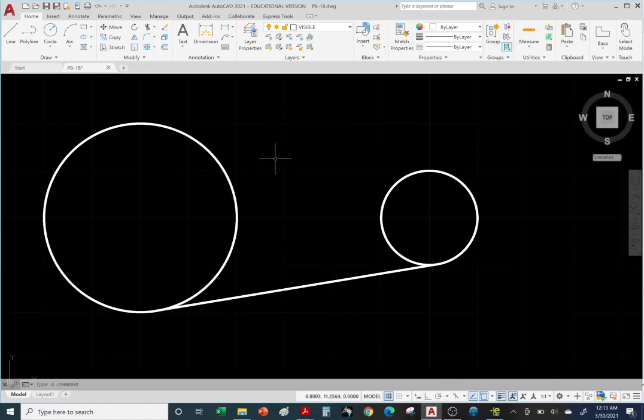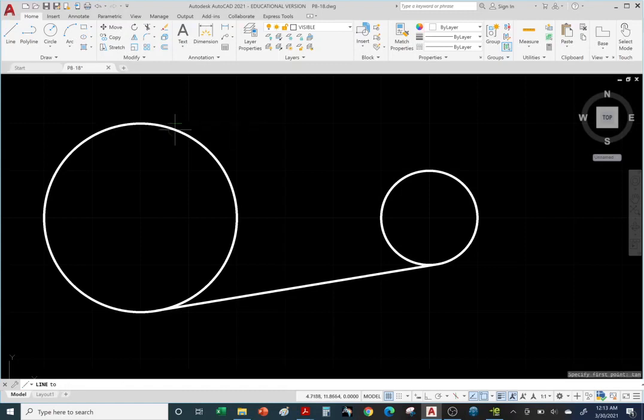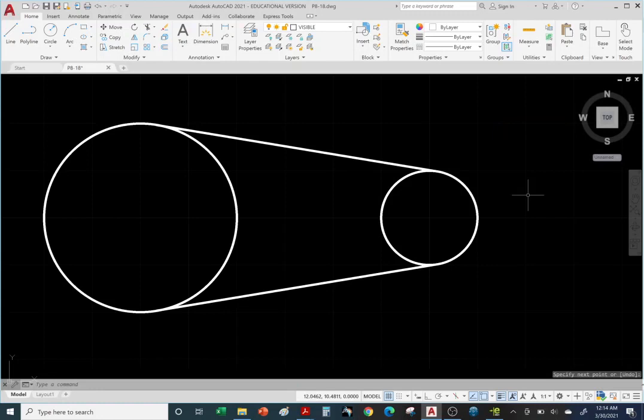So let's repeat the same thing at the top. Line command, then type in TAN, enter. And look for the green lantern ring, which guarantees tangency, click. So now it's tangent to the top. Now let's go over to this side, type in TAN again, enter. As long as you click anywhere on the top portion of it, in 3, 2, 1, click, see how it adjusts itself to intersect at a tangent point. Now we can right click enter to exit.